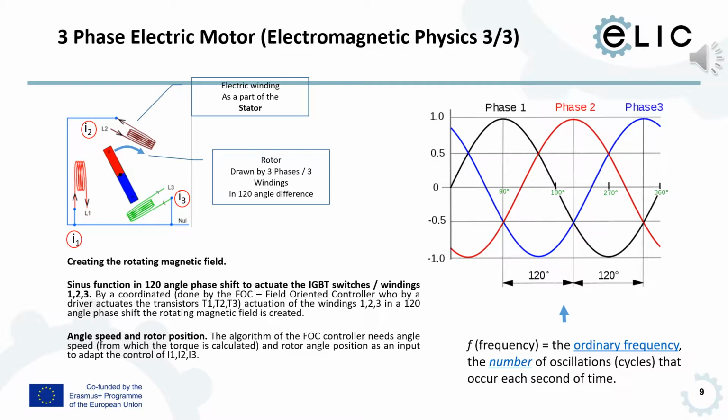And there is a mathematical algorithm behind it, which is basically, in a 120 degree phase shift, these switches are actuated. We will later, in the more physical slides, because we have an extra slide set for teachers in physics, explain that this shift is done by PWM, which is a special method to actuate the switch only at specific times.